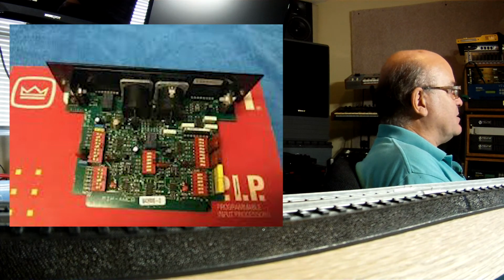Other than the basic need to separate high frequency and low frequency information, as we explained in the previous episode, impedance is always affected by frequency, which means that a woofer type speaker will not efficiently reproduce high frequencies, and the compression driver / horn will not reproduce low frequencies. If we send low frequency information to a tweeter or a compression driver, eventually you will burn it out, or at the least warp the diaphragm. In any case, the component will be trashed. This is the other purpose of the crossover.